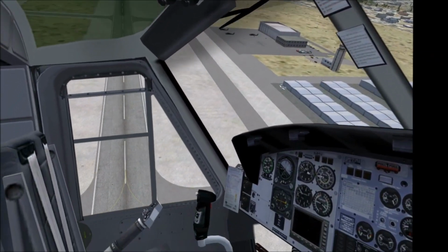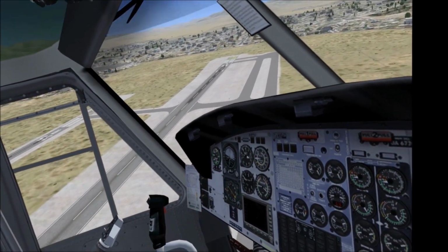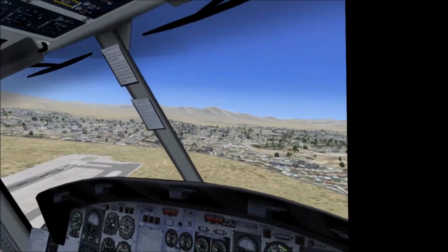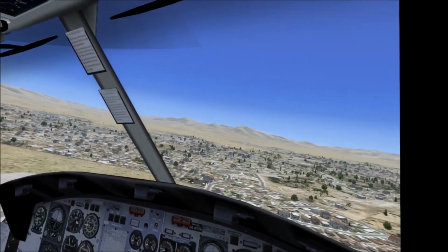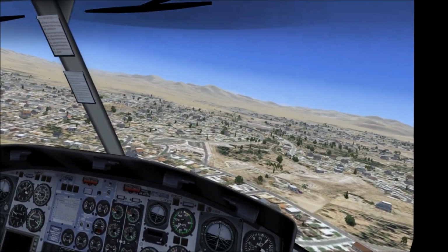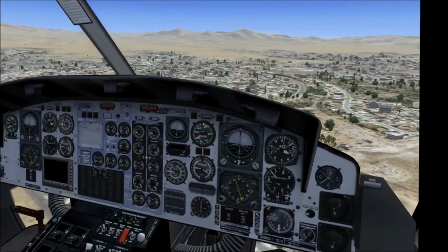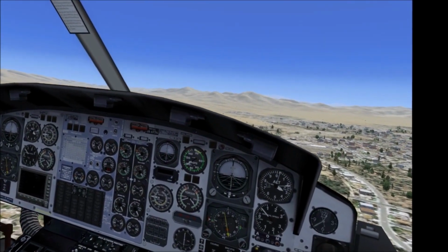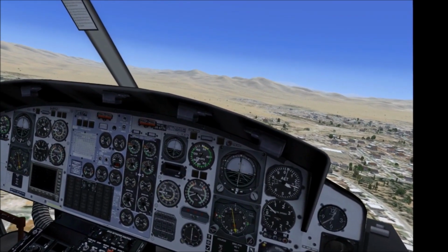And we're going to start our auto rotation, or attempted auto rotation. We'll use 3.6 right, 3.5 left, because I think it's a little longer. That'll give us a little bit more space to work with. So, based on what we saw at flat pitch on the ground and at a hover, I am not sure what I'm going to see when we roll this throttle off. Okay, so I'm going to slow down just a little bit. We're going to enter this auto rotation around 70 knots-ish.